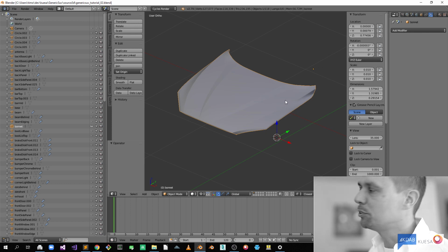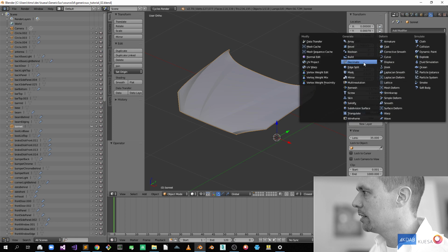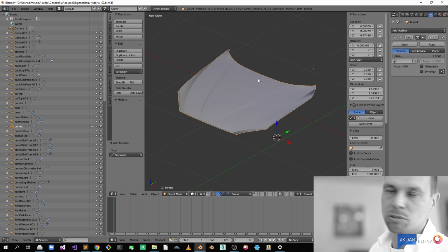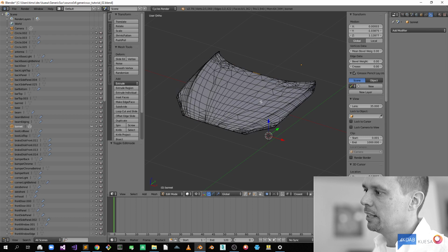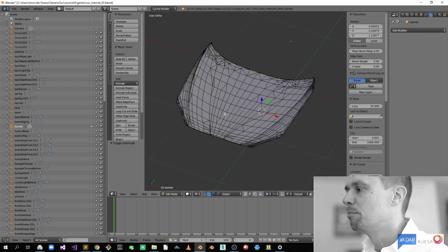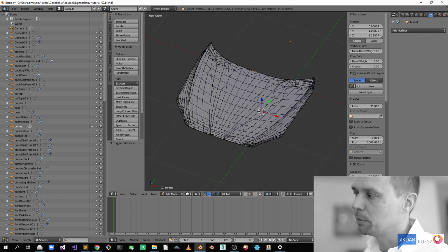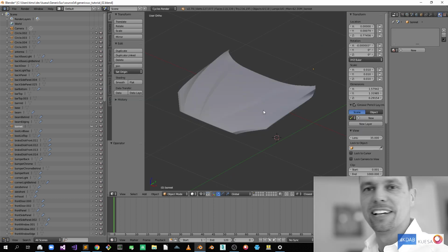Please stay away from using those automatic mesh reduction tools because you absolutely don't have any control over the mesh. Let's apply one of those to this mesh and hit apply. And as you can see, we went from our beautiful regular quad mesh to an uncontrolled triangle mesh, and you definitely will see this later in the reflections in your real-time application.